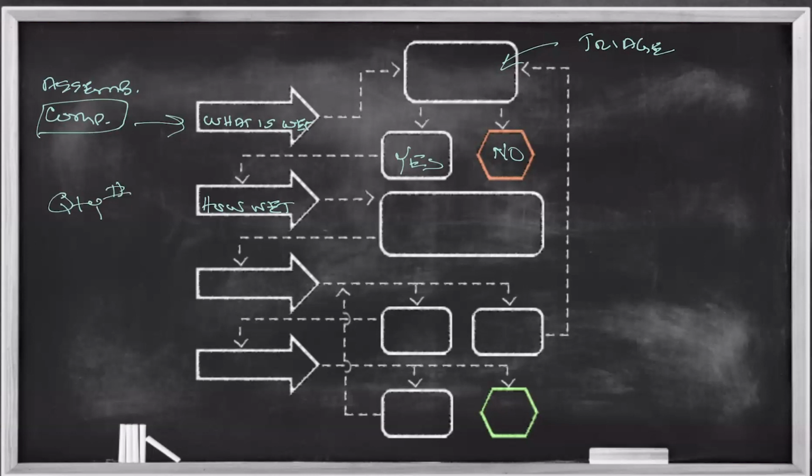Right, and this is another area that we could spend a lot of time expanding on, the critical nature of just how important this is, but I'll just share with you for a moment one of the common mistakes that I think we make as an industry a lot, and that is going out to a project on day one, establishing that an area within a room is wet and affected. It's obvious because I see pools of standing water. We extract, right? We place our drying equipment, and nobody bothers to break out a moisture meter because it's obvious, right? The floor is wet and had a puddle on it, right? A big old puddle right in the middle of the room. So nobody breaks out a moisture meter and tracks a number.